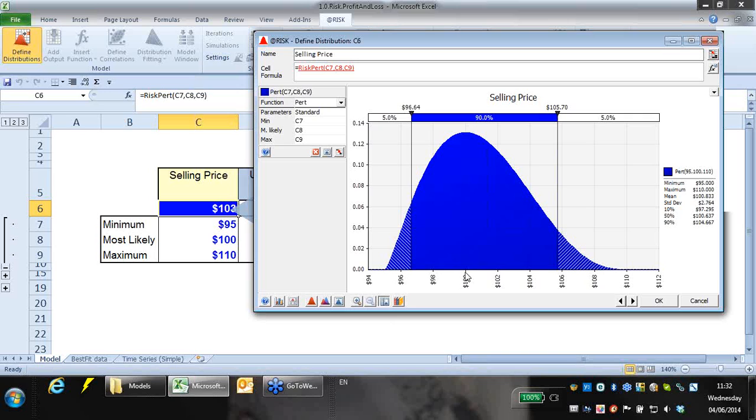First of all, there's a random number generator contained within the software, this Monte Carlo simulation or Latin hypercube in this particular case. That number generator takes samples in conjunction with the type of probability distribution, so it's taking samples which are based on the shape of this distribution. What we can see is that these areas out here, off towards the extremes of the distribution, are what we would call the tails. So these events are less likely than this big area here. Essentially the higher the graph is at any one point, the more likely it is that the samples are going to come from there than from here.